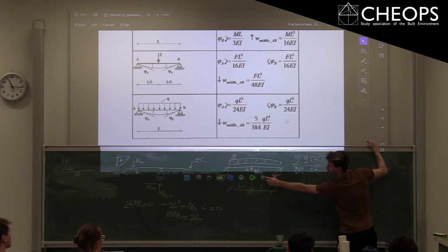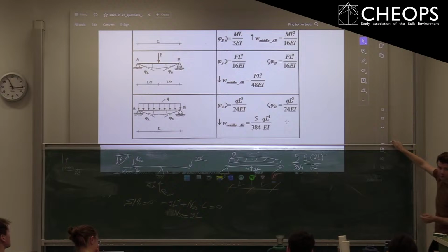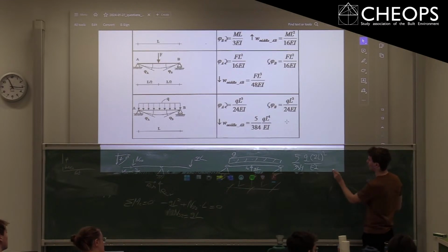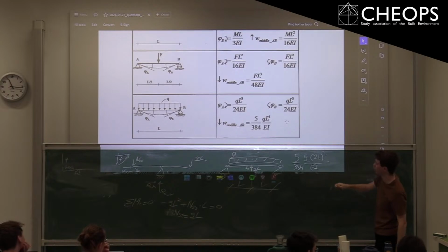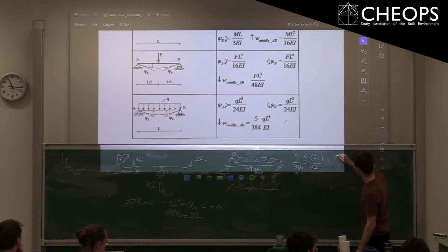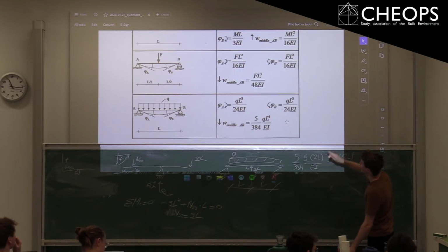Then you also had that QL due to that, well, S1, S2 member, and this is also why that other part of the multiple response was wrong, that actually counters that displacement is due to your distributed load. And for that you use the second one, or well, the first one actually on the screen, where F is in our case QL, that was the one we calculated, times, well, L to the power 3 is 2L to the power 3, and then divided by 48 EI, right?